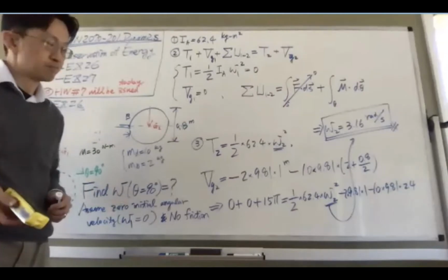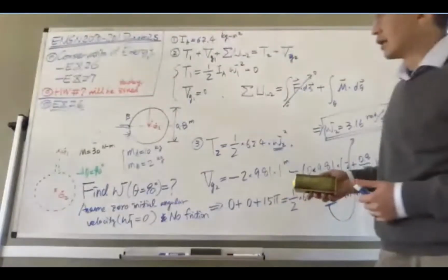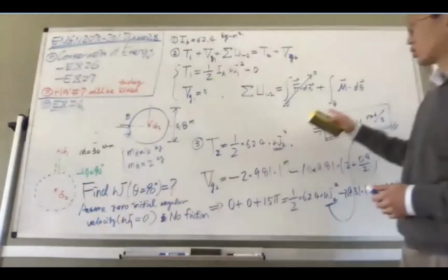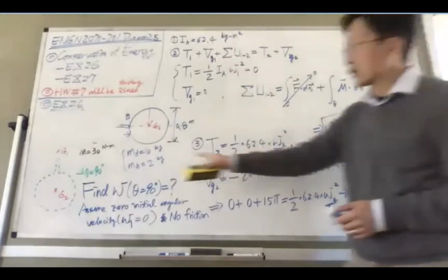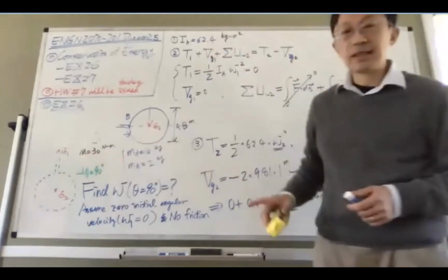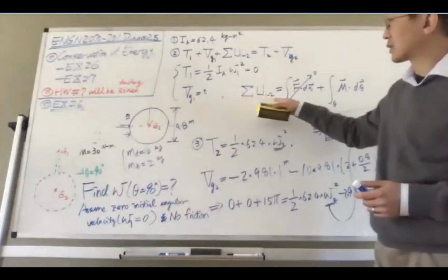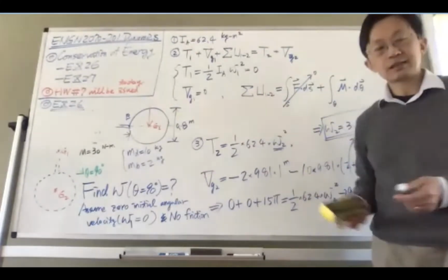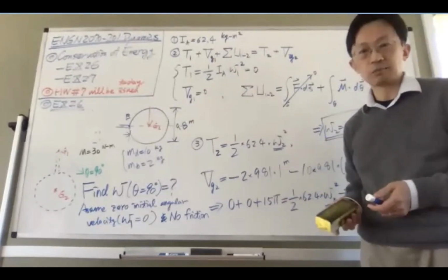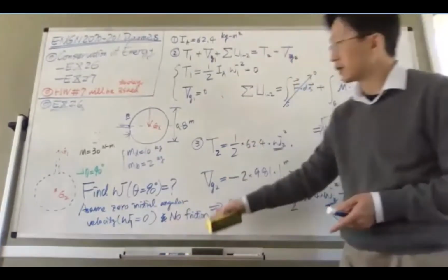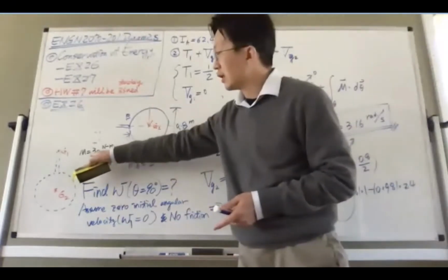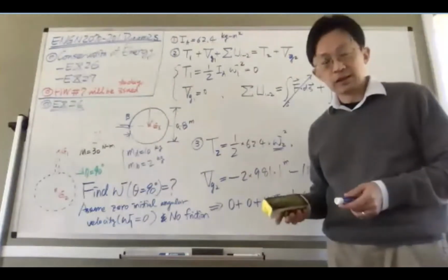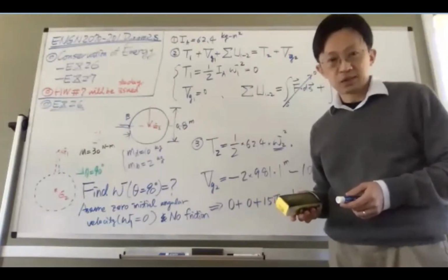There's always friction. So one case you may want to consider is that there may be some friction at this hinge support that can actually reduce the application of this moment. In that case, the work produced by external forces will be less than 15 pi. And that is the case when you consider friction. In this case, we do not consider any friction. Therefore, the work produced by the 30 Newton meter moment is just 15 pi. But if there's friction, this 15 pi will become smaller.